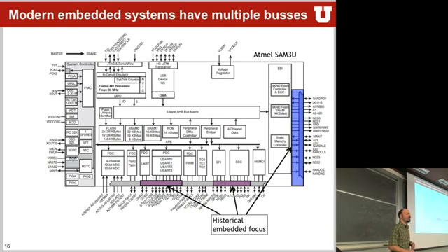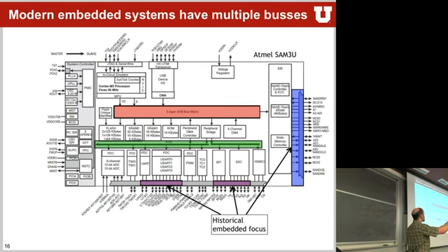In this particular lecture, we will talk about internal buses. In this particular case, the AHB bus matrix that connects our core to fast, high-speed peripherals. And we will talk about the APB bus, which is the peripheral bus that connects the core to slower-speed peripherals that don't need as fast access as some of the other peripherals that sit up here. For example, up here on the AHB, we have RAM, ROM, a DMA, and sometimes high-speed Ethernet. On the APB, oftentimes you have all the slower-speed UARTs, timers, etc. So this is the focus of this particular lecture.